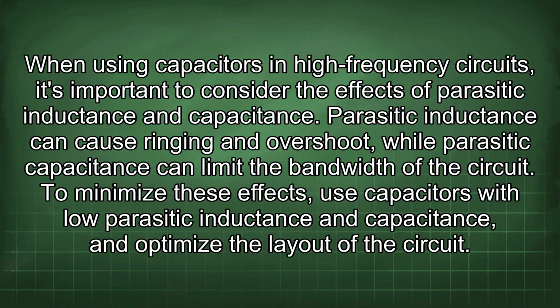When using capacitors in high-frequency circuits, it's important to consider the effects of parasitic inductance and capacitance. Parasitic inductance can cause ringing and overshoot, while parasitic capacitance can limit the bandwidth of the circuit. To minimize these effects, use capacitors with low parasitic inductance and capacitance, and optimize the layout of the circuit.